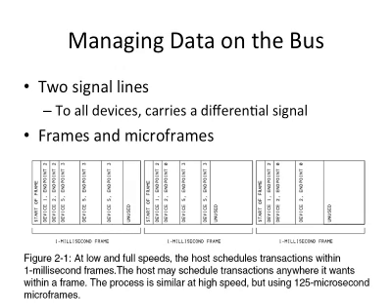In one frame, you can see that we have a start of frame flag followed by different transfers. And what we see here is device 1, endpoint 2, device 2, endpoint 2, etc. We'll see shortly that device ID and endpoint ID are the way to identify the communication endpoints.